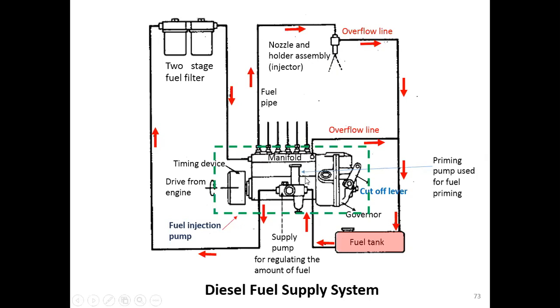Okay, so look at the pump. Back to the pump here. So this is the governor part of the pump, that controls the functions of the pump, so controls how the pump is working. And this gives power to the pump. It's driven from the engine, which also provides the timing device here.